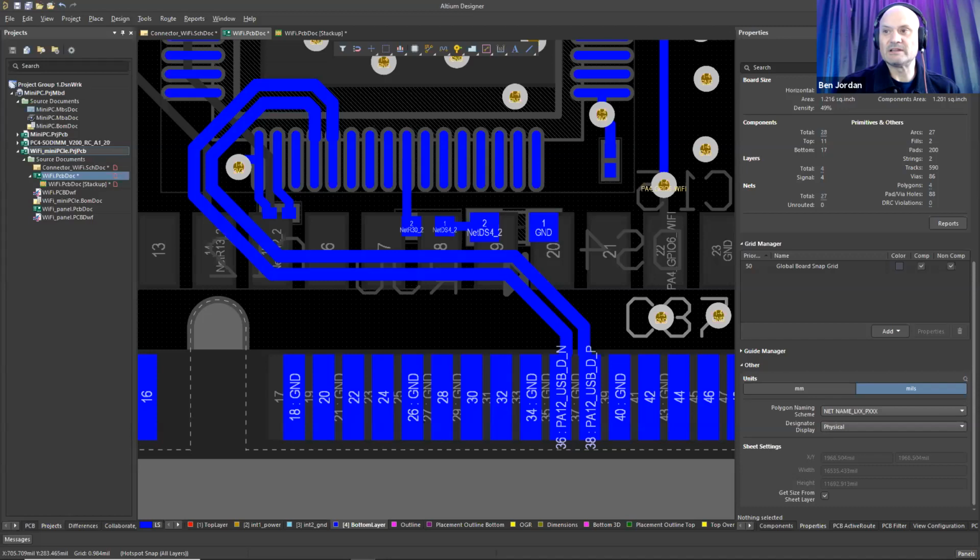At this stage, I believe those are static in our field solver and our material library, because the only fields you enter when going into the layer stack material library are static, a single DK and a single DF, but you specify at what frequency. I'm hoping that we release an update which allows a curve to be put in.